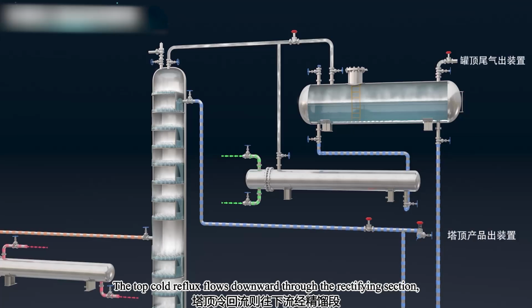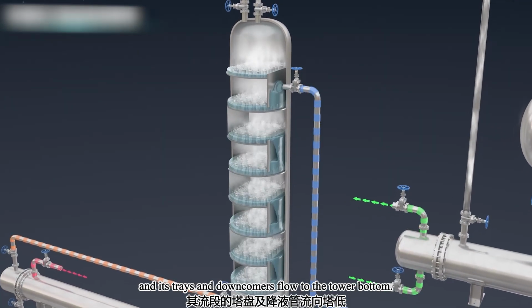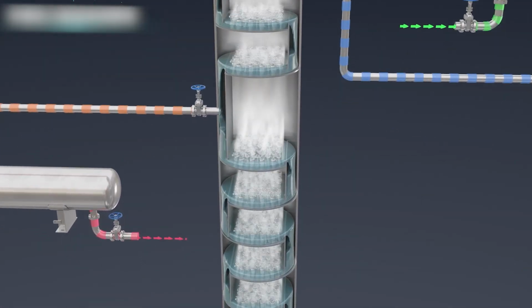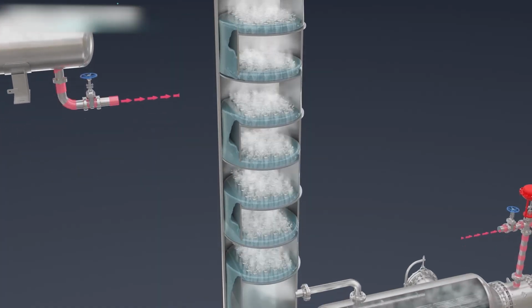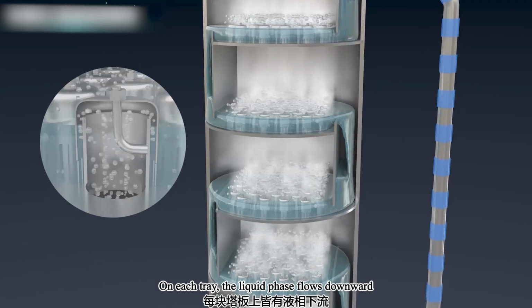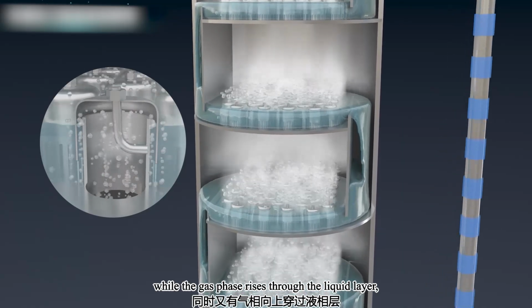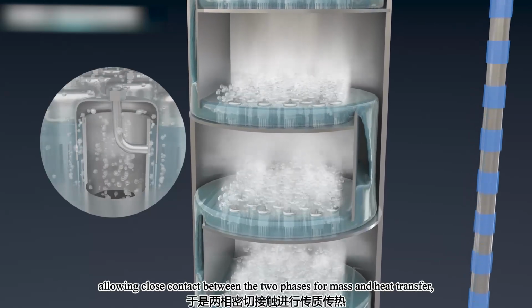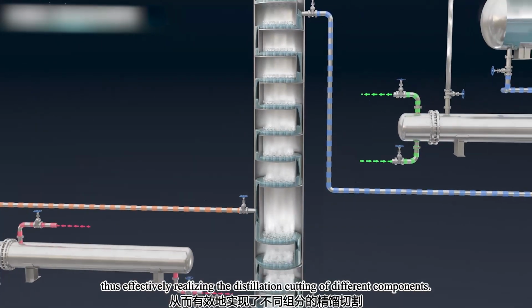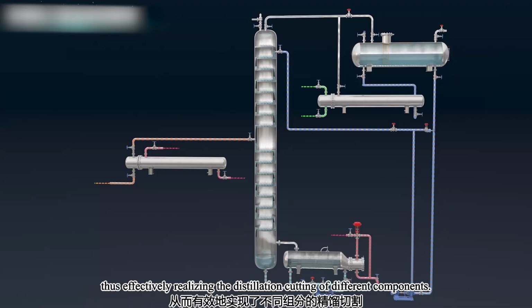The top cold reflux flows downward through the rectifying section, and its trays and downcomers flow to the tower bottom. On each tray, the liquid phase flows downward, while the gas phase rises through the liquid layer, allowing close contact between the two phases for mass and heat transfer, thus effectively realizing the distillation cutting of different components.